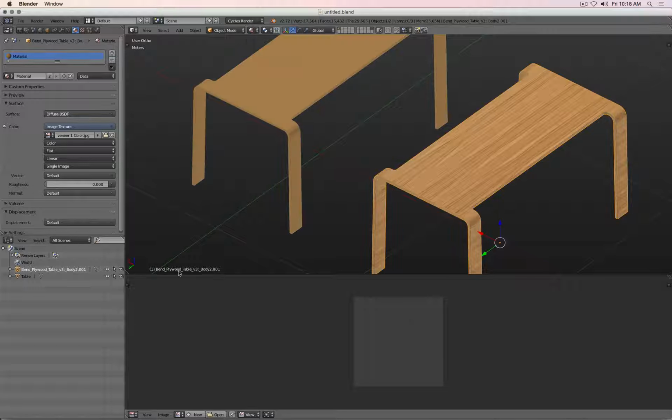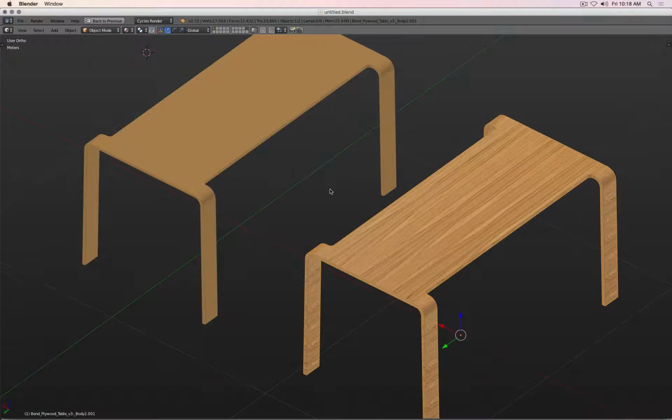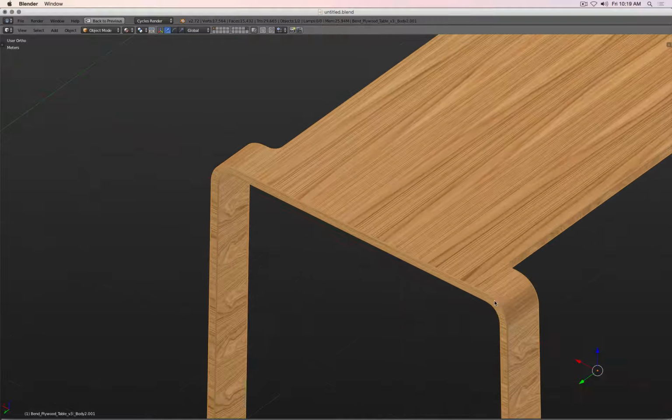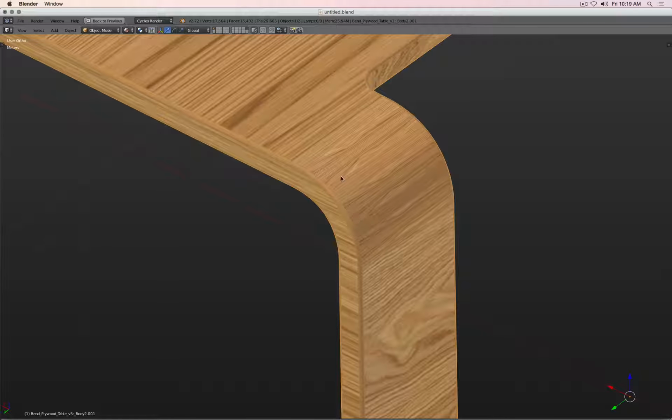If I now set this one to the material preview, it doesn't look too bad. Obviously, the Fusion one doesn't really have any UV coordinates, so no software will be able to project that texture correctly over the polygon mesh yet. And MOI actually wrote that UV map for us, but the problem, as you can see, is if we zoom in, we start seeing that maybe some of the scale issues are off.